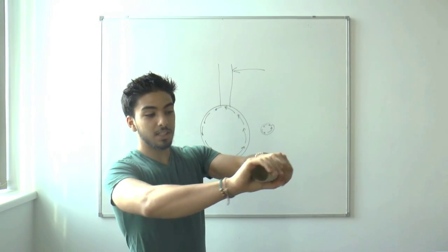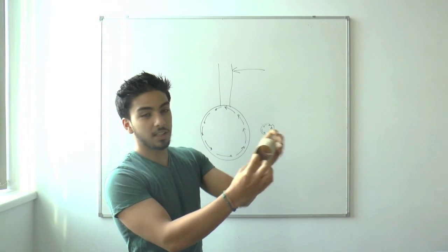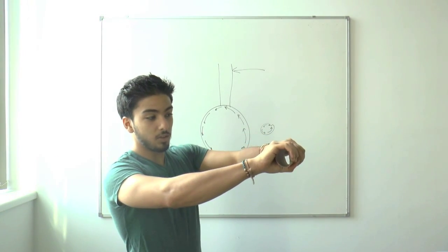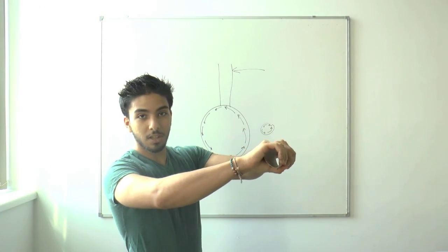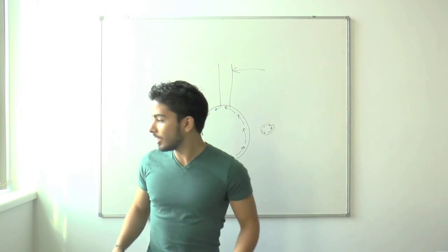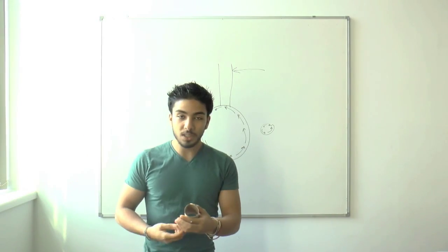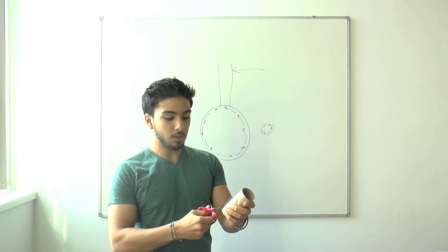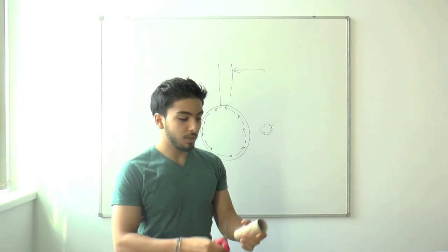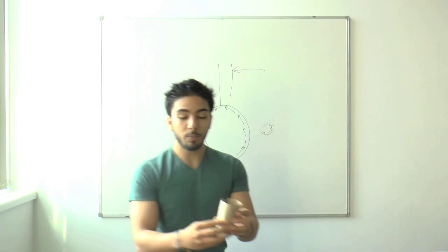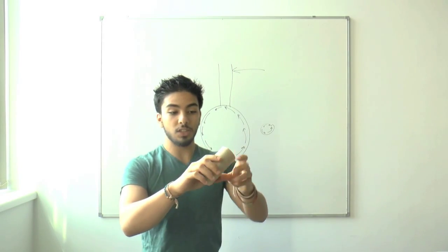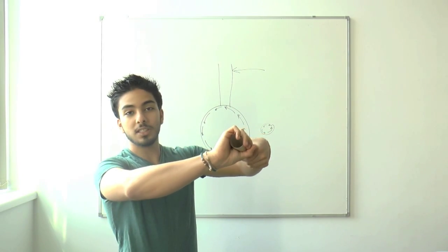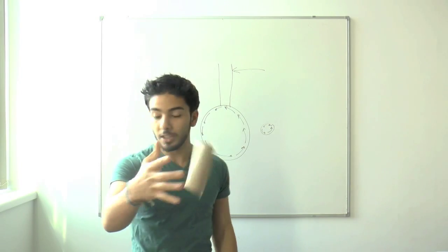And as you can see, although it's flimsy and slender, it has quite good resistance towards torsion. But what would happen if it wasn't a closed section? What would happen if it was an open section and it tried to resist torsion? As you can see, it fails horribly.